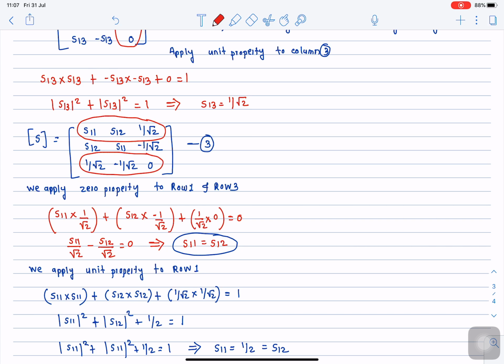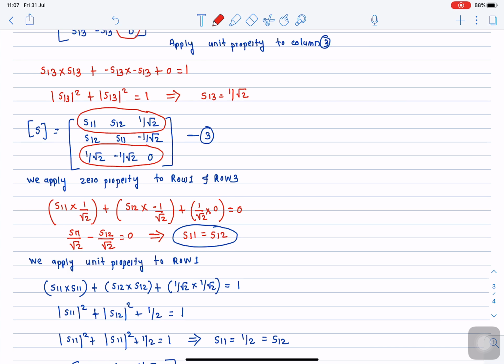Now these devices are extensively used in applications like power dividers. In a power divider you can combine and you can divide and split the power also. Another important application of these 3-port T's is in the duplexer circuit. So what is a duplexer circuit? A duplexer is a device which allows a single antenna to be used for both purposes, as a transmitter as well as a receiver. That can be done with the help of these 3-port junction devices.